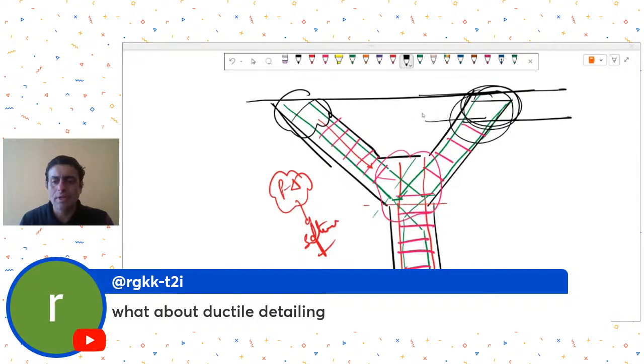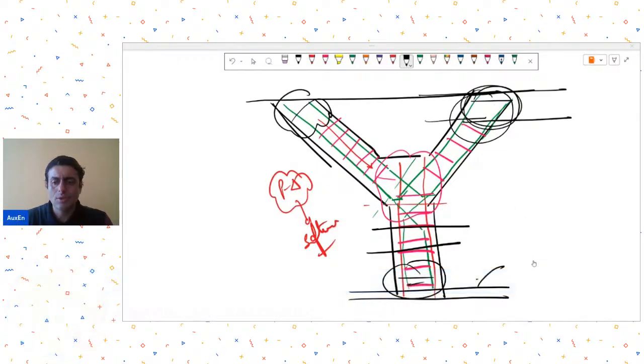So for ductile detailing, you may like to follow all the provisions that are given in the code for a normal column. And for this section also, whatever is the beam arrangement over here, accordingly check for joint shears, etc. So these are my initial thoughts on your query, although in none of the projects I have used such a column till now.